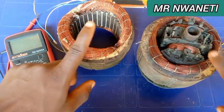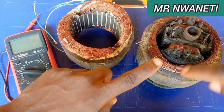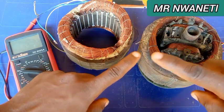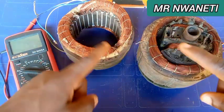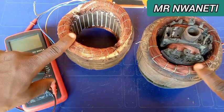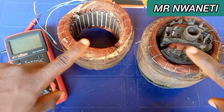In the previous video I displayed a coil of 100 turns. Aluminum gave me almost 2 ohms, while copper gave me 1 ohm. So if you use those two wires to make a generator, aluminum will have double the resistance. Copper is more conductive.